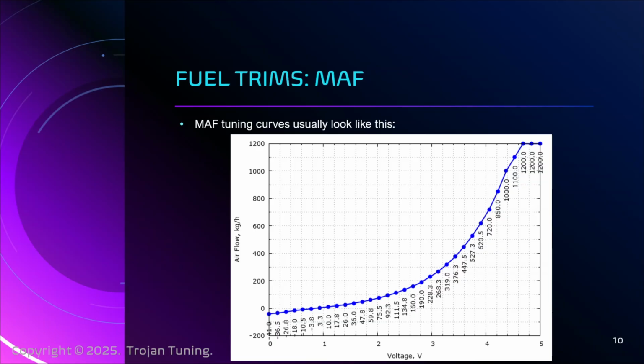And the computer sends voltage into that pin, which causes it to heat up. If there's a little bit of air, I need a little bit of voltage to heat up to reach a balance point of what the temperature of the pin was before the air started flowing over it. So if I have a little bit of air, I need a little bit of voltage to heat it up to reach that point. If I have a lot of air, I need to send a lot of voltage into this little pin to reach that break point, right, of prior cooling.